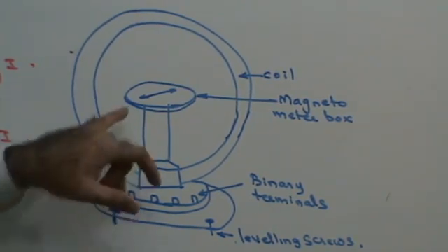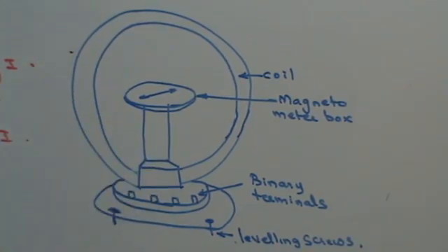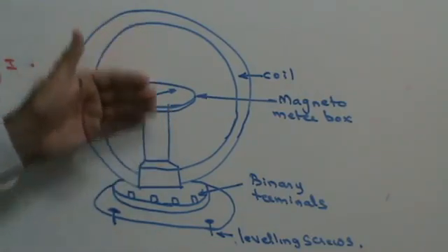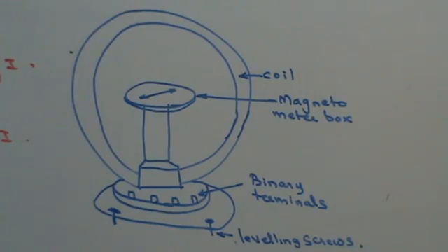A short magnetic needle is placed at the center of the coil and can rotate in the horizontal plane. A long thin aluminium pointer is pivoted at right angles to the needle and shows the deflection, which is divided into 4 quadrants of 90 degrees each. A plane mirror is kept below the pointer, which helps to measure the deflection without parallax.